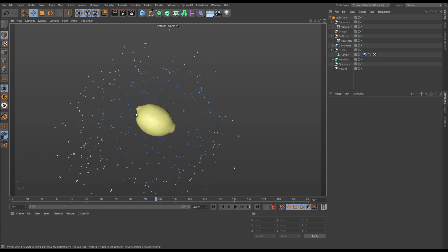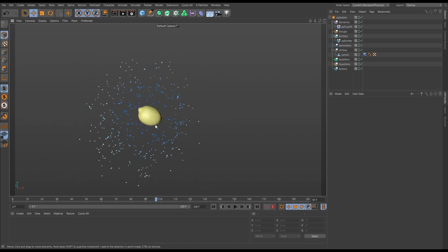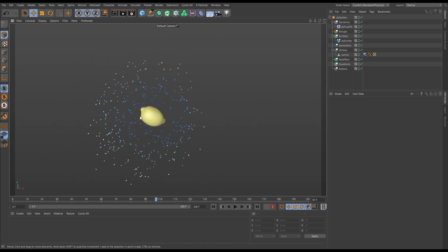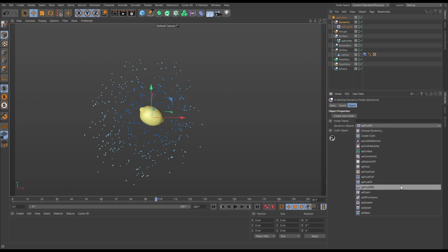splash on this fruit, and we've all seen these product shots for drinks and the like. So what we want to do is use our sheeter tool to fill in the gaps of this fluid simulation to create a sheet, a splash of water. So let's go to our dynamics. We're going to go to our dynamic objects and we're going to pick an XP sheeter.